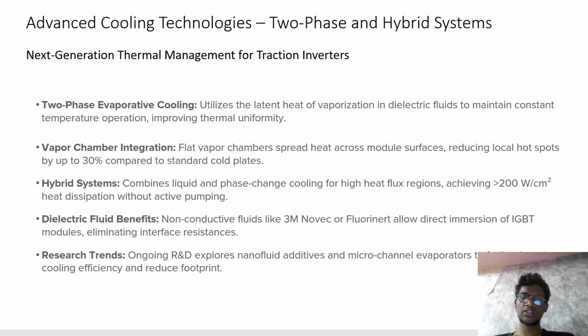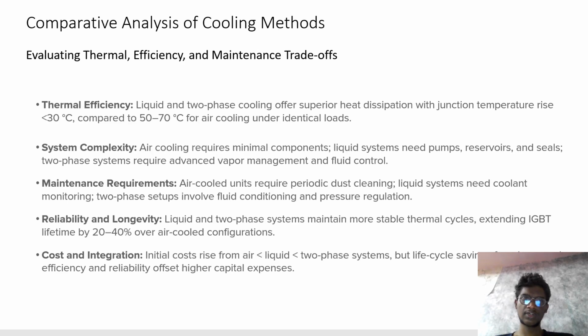Advanced cooling technologies: two-phase and hybrid systems. Two-phase cooling exploits the latent heat of vaporization in dielectric fluid to maintain constant temperature operation, improving thermal uniformity. Vapor chamber integration, hybrid systems, dielectric fluid benefits, research and trends. Comparative analysis of cooling methods: thermal efficiency, system complexity, maintenance requirements, reliability and longevity, cost and integration.